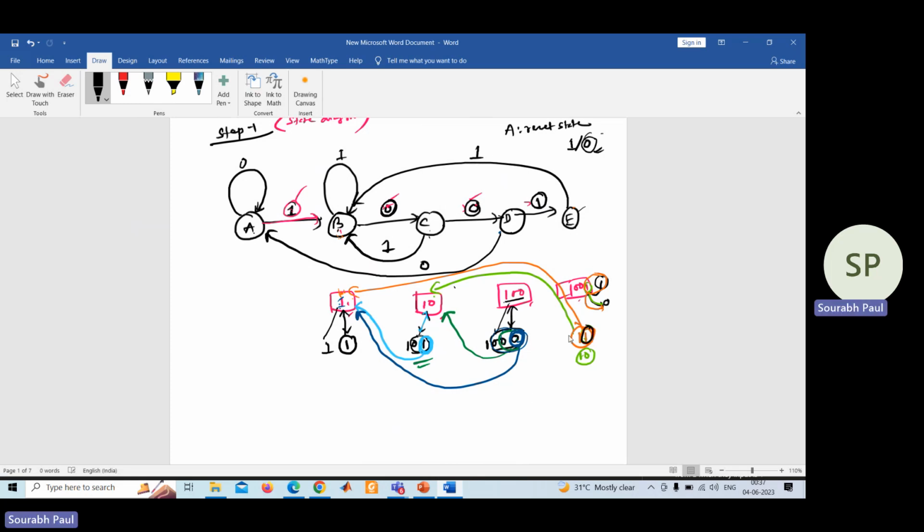Okay. So this part we have completed. Now come to the other combination, that is 1, 0. So 1, 0 is a 2-bit state. You need to compare with the 2-bit state, that is 1, 1, 0. Are they matching? Yes. So it means that from E to C you need to come, because 1, 0 represents this C state. So from E to C you need to come when you have considered the input of 0. Okay. Any other state left in this diagram? No. So it means that we have got the state diagram.